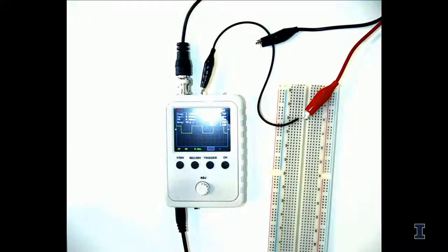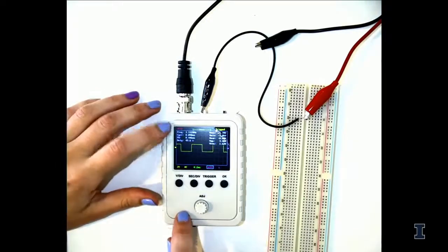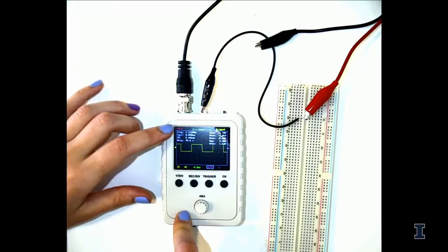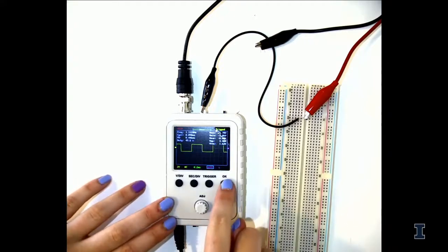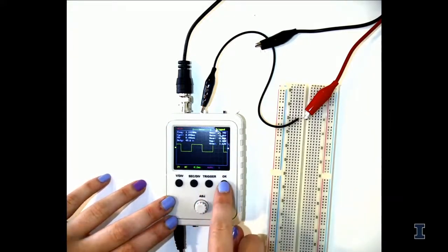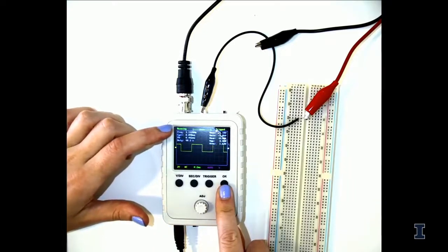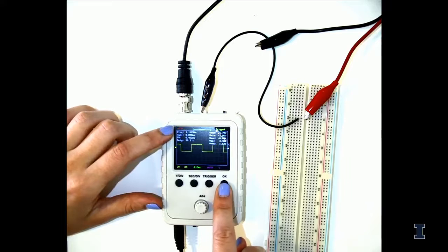And you'll notice that the signal has stopped moving around. This is because the oscilloscope has set it to hold. So it's going to hold your signal in place at that one time that it stopped. In order to start running the oscilloscope again, we get out of trigger and we press OK. And now you'll see in the top left corner that it says running. If you want to stop it again, you just press OK, and it'll go to hold, and your signal will freeze at that point in time. Then we can have it running.